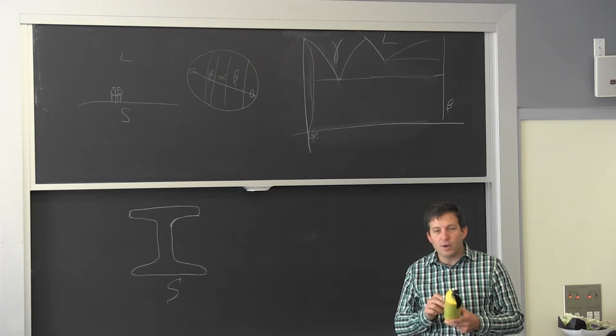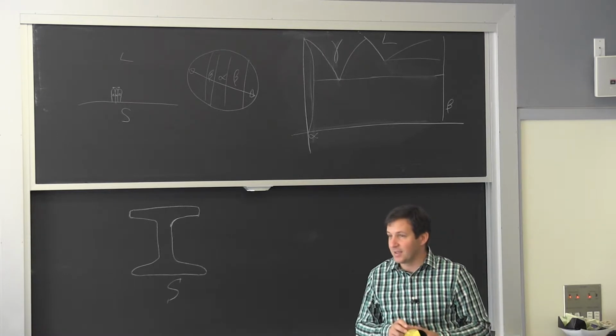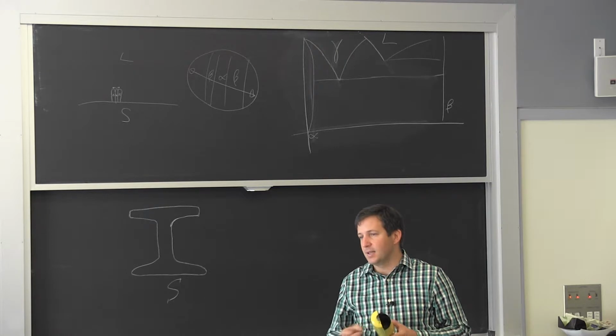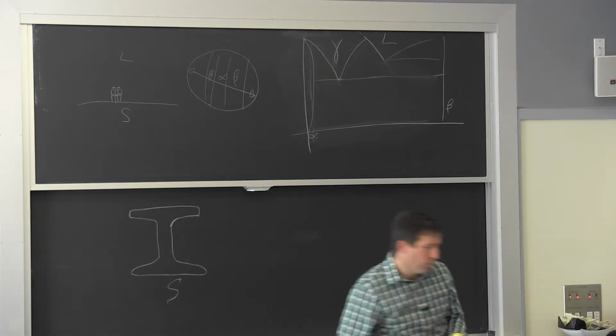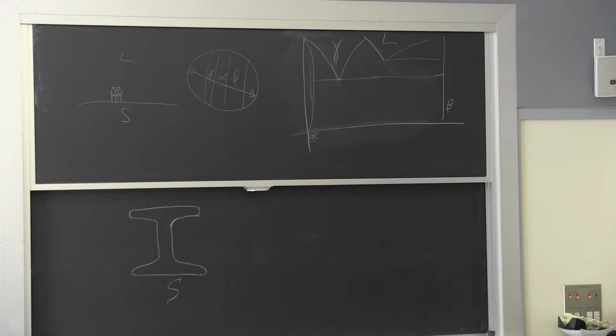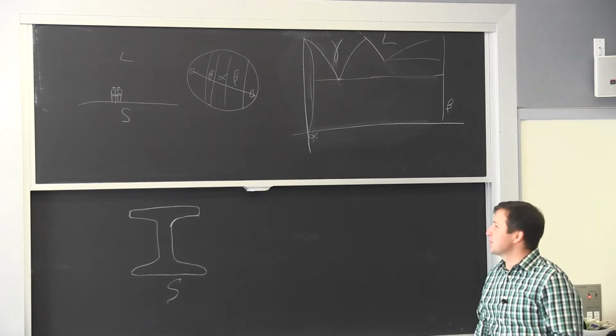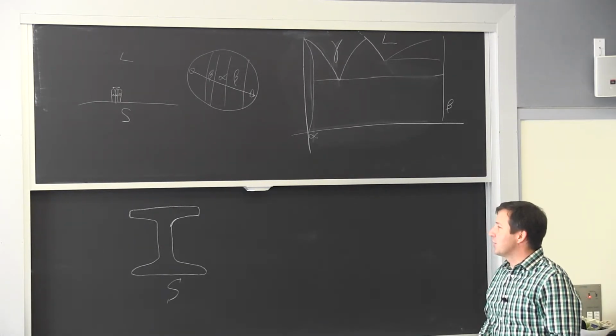If you lose the hardening, it's like our tensile test. You have that local instability, and then it's cracking at one point. So the aluminum is the same. You use aluminum alloys that will harden during deformation. If you try to do it with pure aluminum, make a can, it's just not going to work. Not enough hardening.